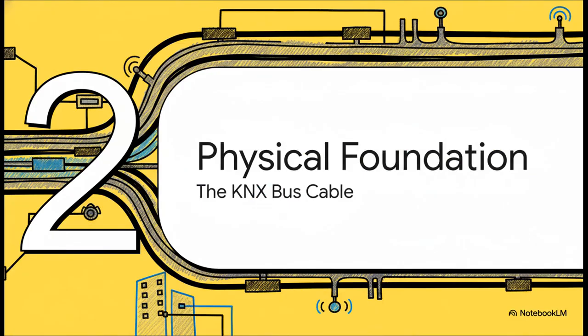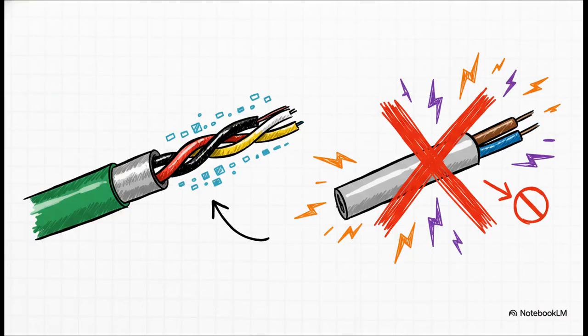So before we can even think about the logical structure, we have to start with the physical layer, the real-world stuff. And it all begins with one single, humble wire, the KNX bus cable. This thing is literally the central nervous system for our entire smart building. Now listen, you can't just use any old electrical wire for this. KNX twisted pair, or TP installations, need a very specific standardized cable. It's a shielded, twisted pair cable designed purely for sending data, not power. And the rules are super strict. You absolutely, under no circumstances, use standard mains cables for the bus line. That's a huge no-no for both safety and for making sure that data doesn't get corrupted.